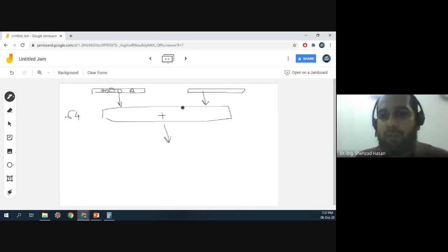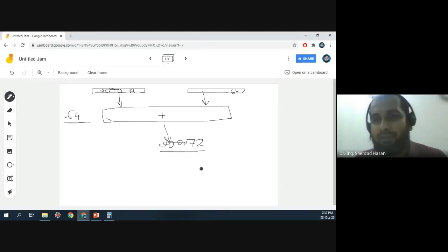If, for example, I need to add 8 with, say, 64, both 8 and 64 can be stored in a single byte, right? But since you have an adder of 64 bits, you are going to have 8 on one side, 64 on the other side, and you are going to get the answer 72 as a 64-bit number, right? Now, what can you think of this? This is totally a wastage of resources, right? Why? Because you have such a big adder and you're just doing a single byte addition on it.